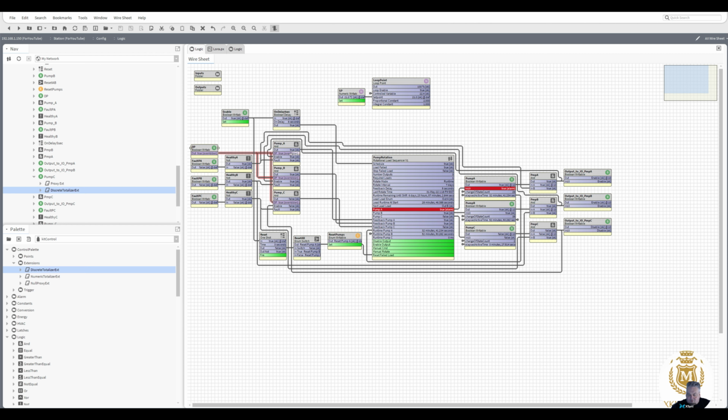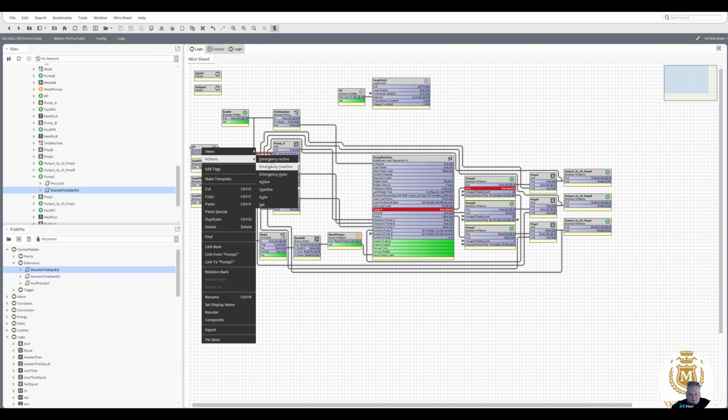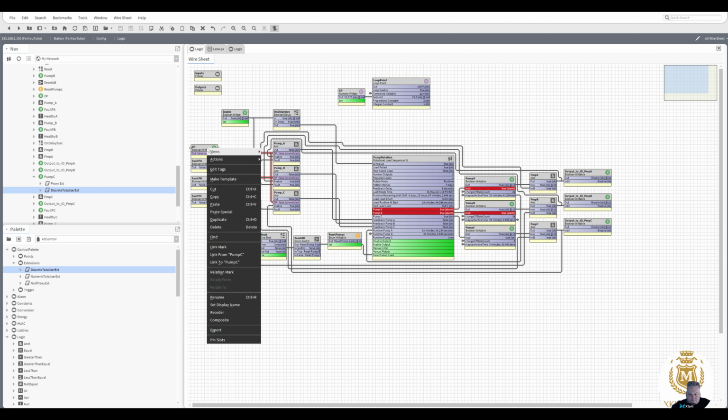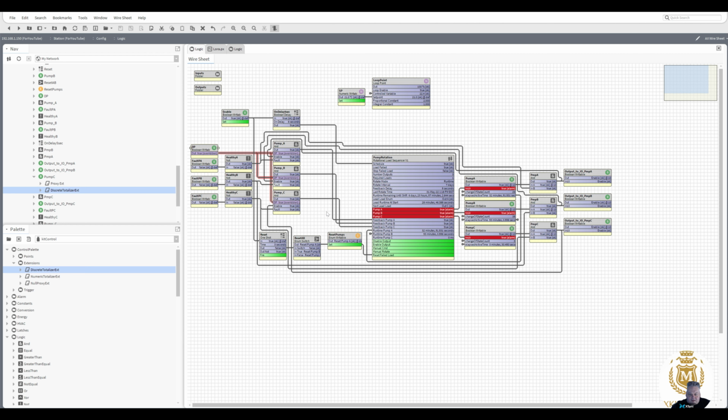We're not in fault. We'll take the DP off. Pump B is going into fault. Put the DP back on again. I wasn't fast enough. I wasn't fast on the 5 seconds, so they're all in fault now. And yet you've still got all these enable, so even though it's in fault, it basically sends an enable out, which we're okay with because we've linked these faults now into not sending the enable, but we've still got 3 outputs at the moment all enabled, and yet they're in fault.